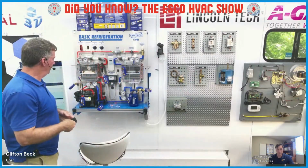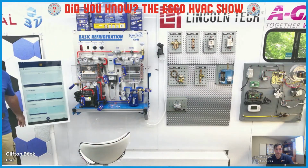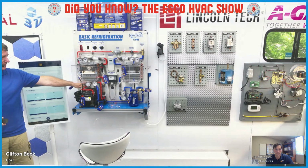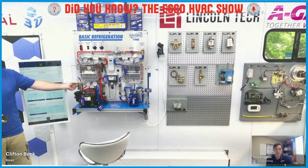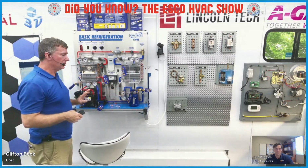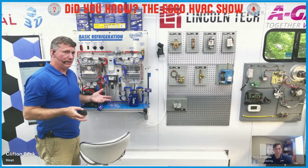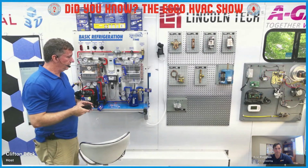So if I move over on the high side, it's actually tucked back in just a little bit. Now we can see it. This particular one on the high side of our system is right here. So this had been our liquid side, and we've attached our high side over here. That's given us our low side pressure and our high side pressure, just like we were attaching a set of manifold gauges, whether it was a standard set or a digital.